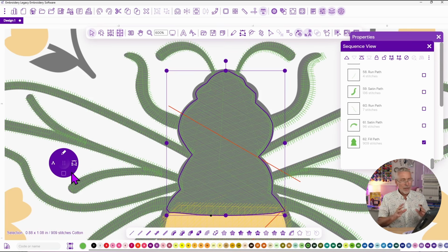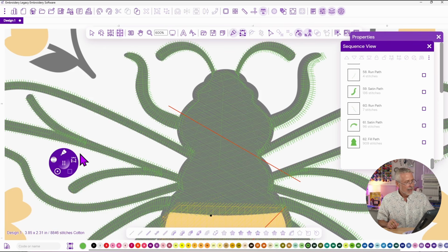Now again, a really quick, easy way to outline this would be to just come in here and choose my steel. I'm going to choose, let's say, 1.5 millimeters, just like I did before, so it's already set up. The software automatically remembers the last property that you chose, and you can choose custom properties that aren't within the widget, and it'll remember those as well. And now all I have to do is come here, start right here, and go right around the outside of the design.